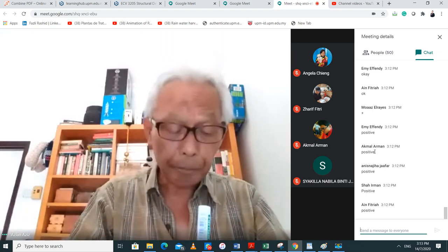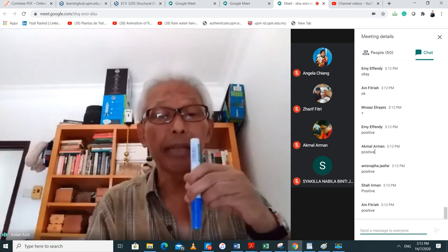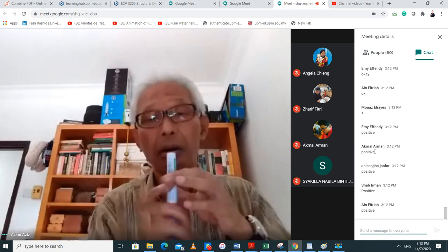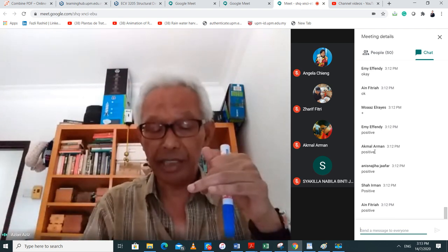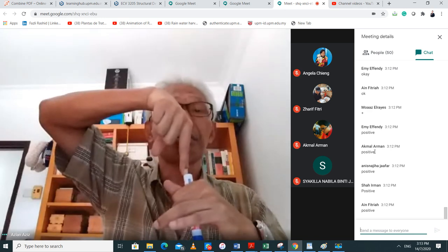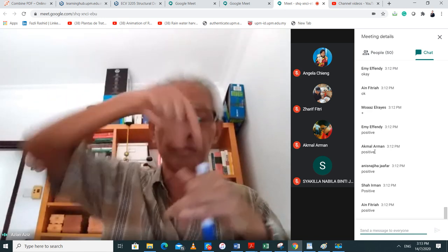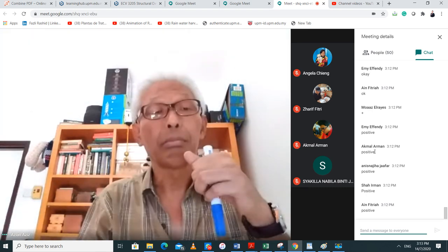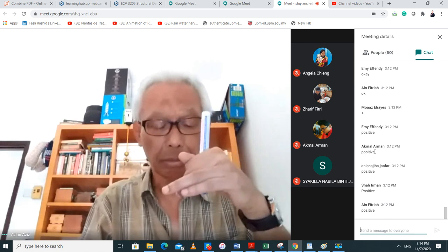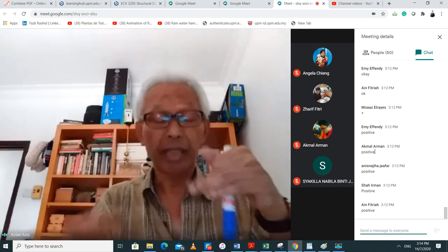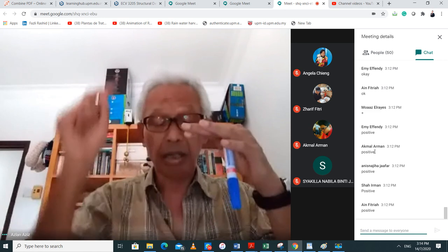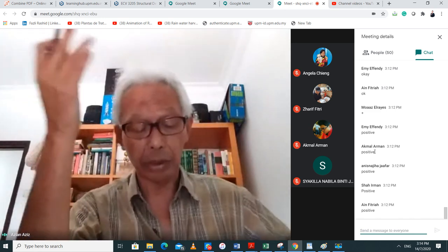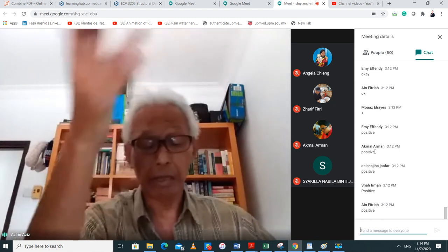And then it says the uplift load. This 1625 from the soil must counter the column load that is given. Then there is the uplift load, which is going to push my pile out. So the skin friction must counter that uplift load. 2.5 is the factor of safety, multiplied by 225, you get 563 kilonewton.